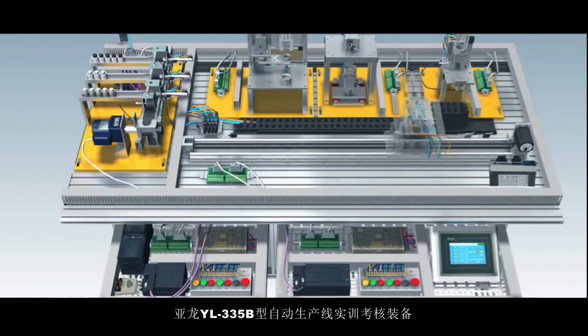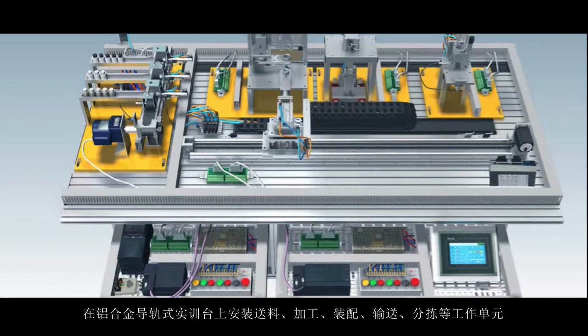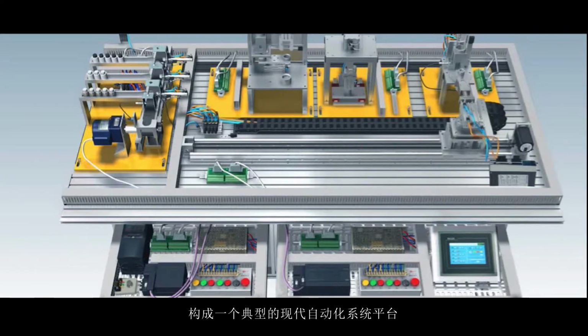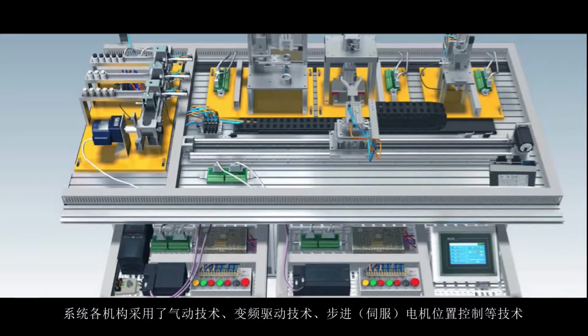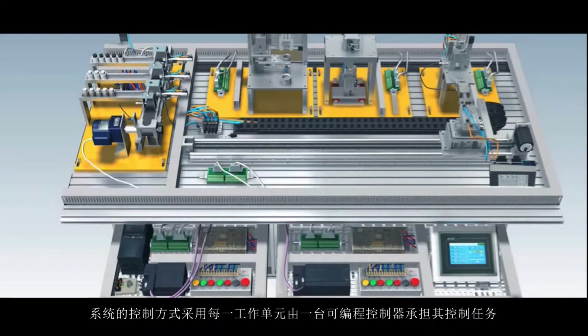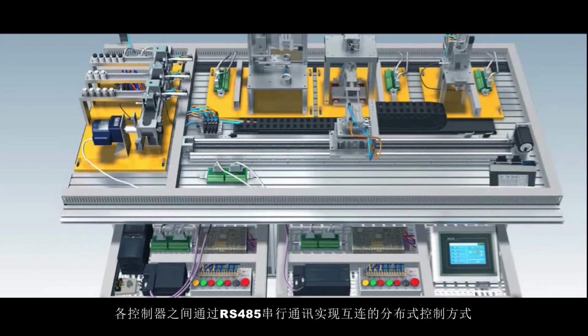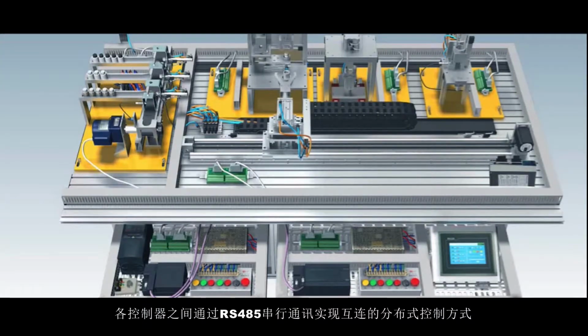YL-335B Automatic Production Line Training Assessment Equipment. Installation of feeding, processing, assembling, conveying, sorting, and other working units on the aluminum alloy guide rail constitutes a typical modern automatic system platform. The system adopts pneumatic technology, variable frequency drive technology, and stepper and servo motor position control. The control mode of the system is controlled by a programmable controller. Through RS-485 serial communication between each controller, the distributed control mode of interconnection is realized.